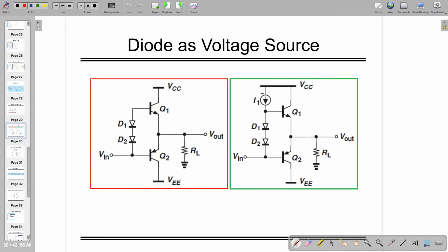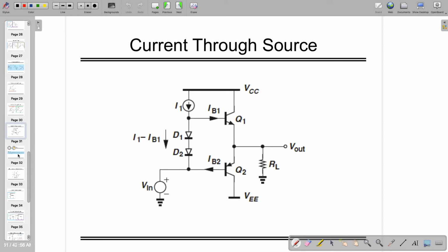So what we can do, you can add one current source on top of that, so that the voltage is going to be developed over here, and that will make sense of having two diodes, and always anode is higher than cathode. So in that case these are PN junction diodes, and when they are on, they are going to give you the equivalent on voltage, which is around 0.7 volt, similar to what we need for the cut-in voltage of the base to emitter junction. So that can be taken by the PN junction of each one of the diodes, where each diode has a cut-in voltage or on voltage of VBE1 and VBE2, which are both equal. And that's what we can do to implement that circuit.